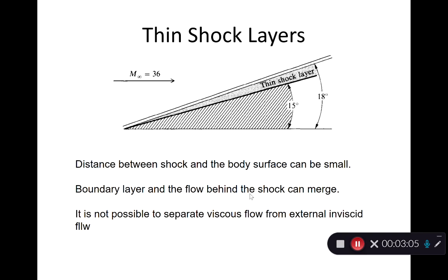So here are some of the features of hypersonic flow. As we first talked about, the shock layer is very, very thin. In homework number 3, you have been doing conical flow, where you're given a theta of the cone, and you're iteratively computing the beta of the shock wave. And in this case, you could see if the Mach number goes to very high, like 36, the angle between the shock layer and the solid wall is very, very thin. So within a 3-degree angle, lots takes place.